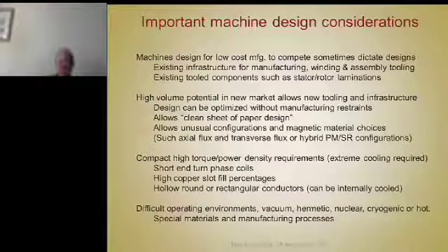So cooling passages are put in between sections of the stator and the rotor core, and fancy pressurized blower systems to blow air, or even large machines even use liquid nitrogen and hydrogen, actually use hydrogen cooling.